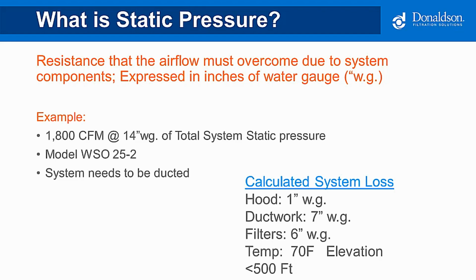This is important to know because the density of the air may be lighter or heavier depending on the location, which can impact your fan design. So depending on where you're located in the country, you need to make sure you convey your elevations and your temperature requirements to your reps when you're sizing a system. So let's look at the components of this particular example.